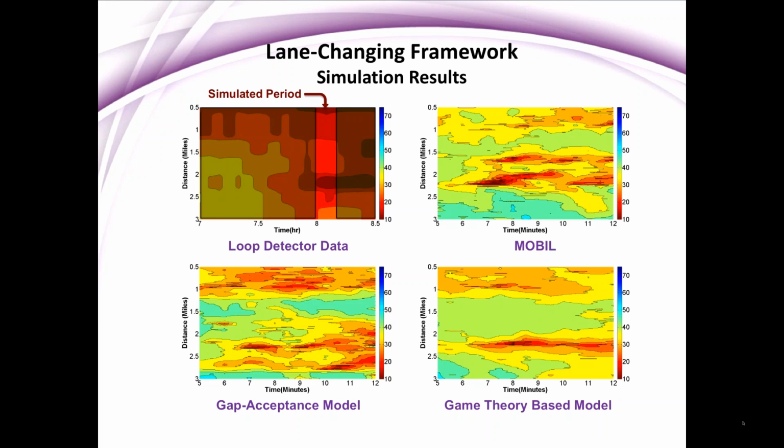There was a congestion at the same location here between 2 and 2.5. The speed here was fairly low, which was compatible. However, there was another congestion here, another on-ramp, which we don't expect to see. Okay, and remember, the seeds for these simulations are all the same, so the vehicles are getting onto the highway all at the same time. It's just the performance of the models that is different.